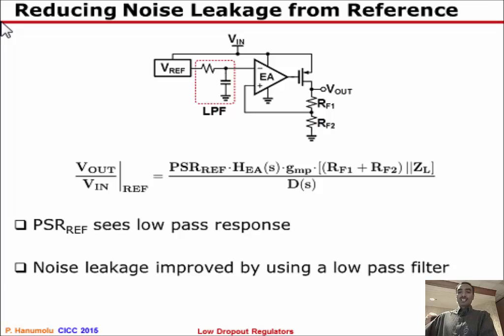Anything that you can do to lower output impedance is naturally going to help the load transient. So if you can figure out a way to combine the series element with the shunt element, that's bound to help load regulation. But I myself haven't designed any of that. So if you have any more questions, you can talk to Eric after this.